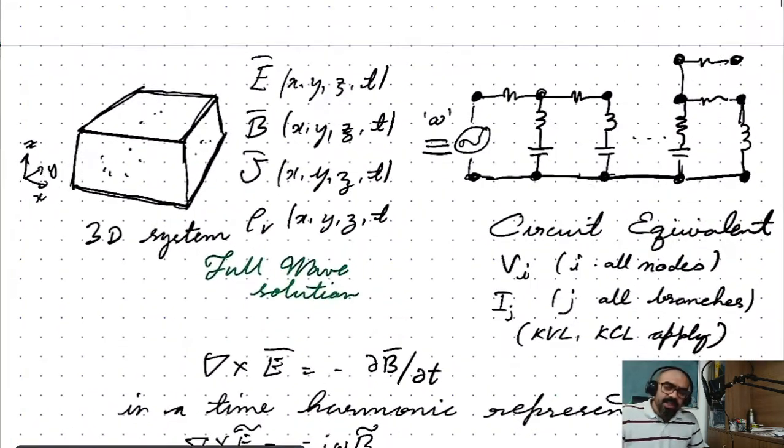I will start by quickly going once again into the approximations that allow us to think of electrical systems as circuits. And going from Maxwell's equations, any electrical system is some region in three-dimensional space, and to do a full, exact analysis, you have to solve for the E and the B fields with inputs as current or charge, for example.